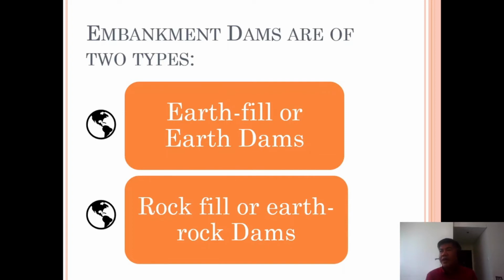So there are considerations to be checked, because as I have mentioned, you have to analyze the slope stability and seepage. In slope stability, what matters most in the Mohr-Coulomb analysis are the input parameters: unit weight, cohesion, and angle of internal friction.